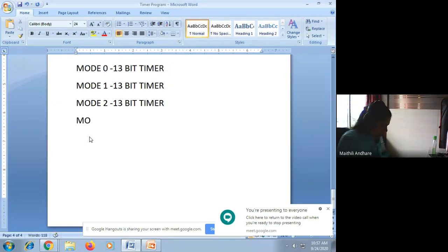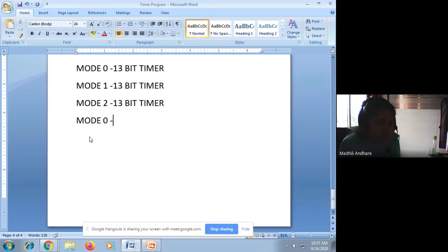काय करायला लागेल? सपोज मोड 0 घेतला मी, तर आता आपण काय करतो, जी काही इनिशियल व्हॅल्यू आहे ती मॅक्सिमम व्हॅल्यू मधनं मायनस करतो, बरोबर. 65536 मायनस FFF2 किंवा त्याचं डेसिमल व्हॅल्यू. आता मोड 0 मध्ये टायमर किती बिट्सचा आहे? 13 बिट्सचा आहे. 2 to the power of 13 म्हणजे किती येतं? 1FFF, आणि त्याची डेसिमल व्हॅल्यू येते 8192. तुम्ही कॅल्क्युलेशन करू शकता. ही टायमर ची मोड 0 मधली मॅक्सिमम व्हॅल्यू आहे.